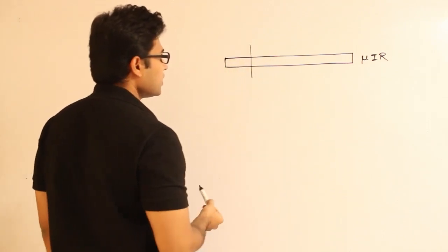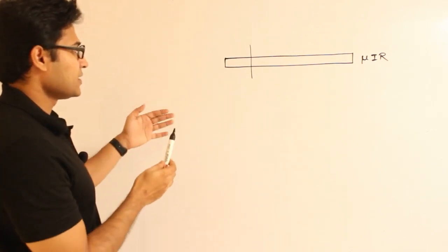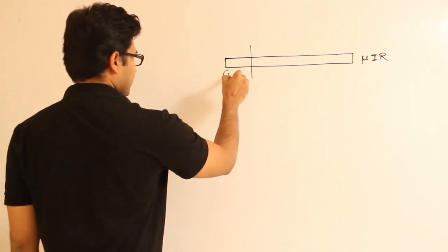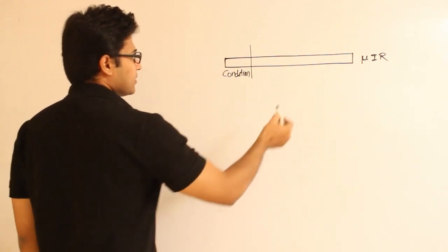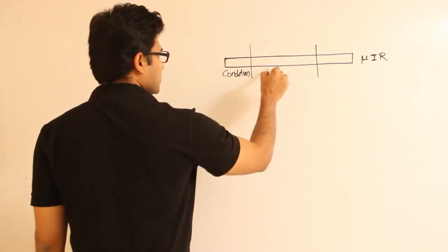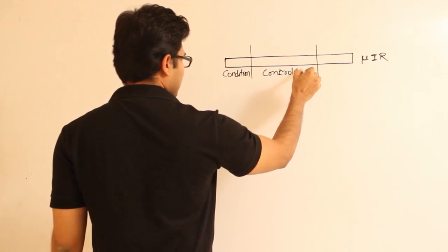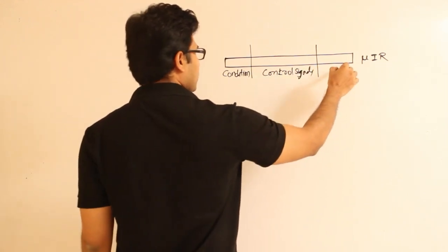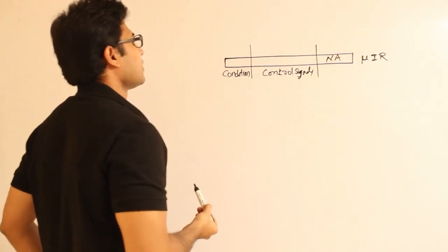The first part is going to be for condition checking, or these three parts can be anywhere. Here in this example I'm just using the first part for condition checking. And this part can be used for micro operation, which means control signals will be generated here. And this part is going to be useful for the next address.